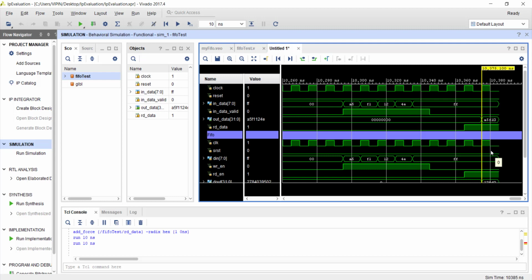Another one that we frequently use are RAMs, the memory itself. You may have to build a small memory inside your IP, especially if you are doing image processing or video processing applications like that. Maybe you want to initially buffer some image data before processing it. The difference between FIFO and traditional memory is that in a FIFO, if you store some data, you can read it only once. Once you read it from the FIFO, it is out of the FIFO.